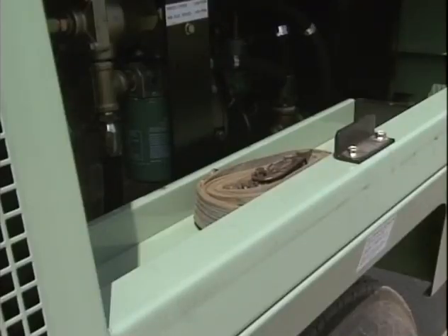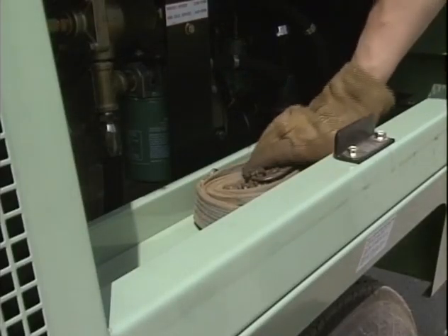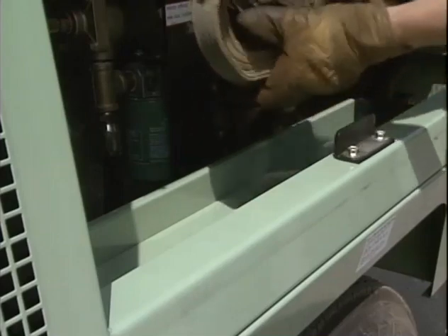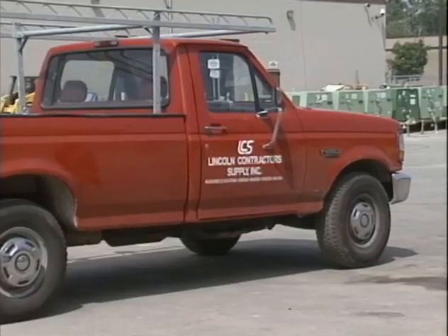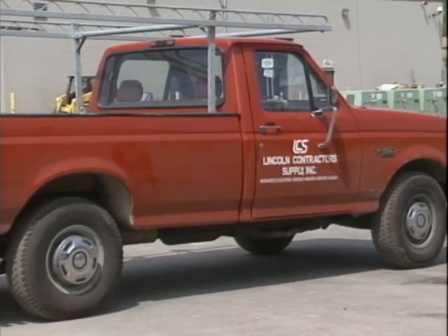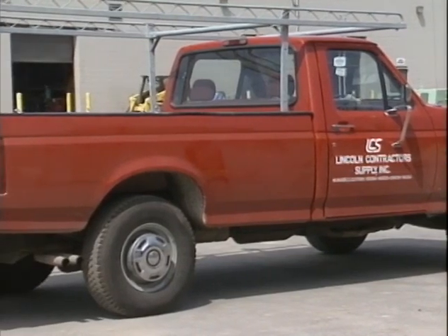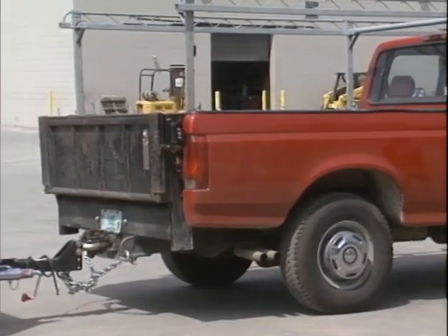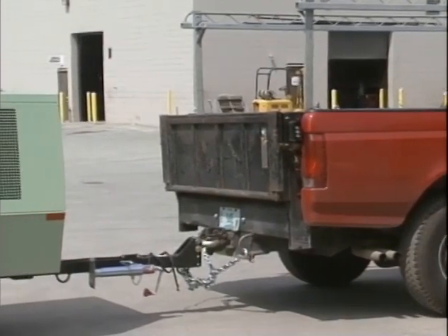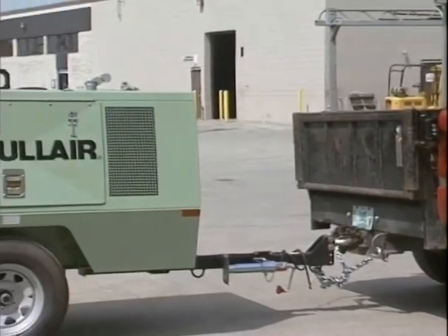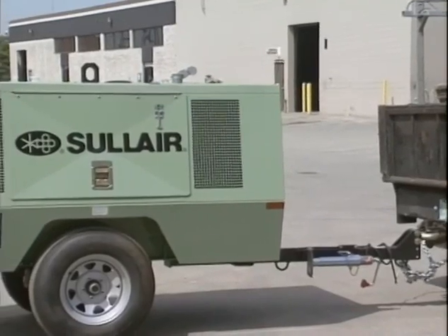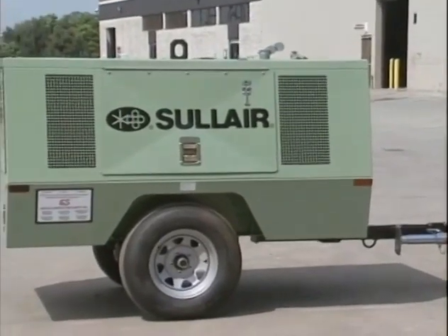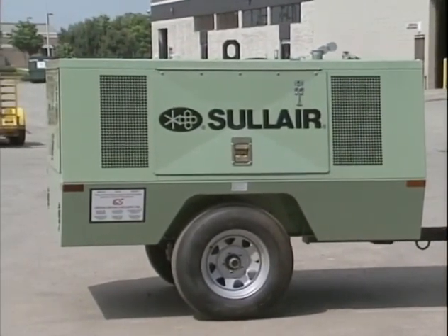Do not carry loose or inappropriate tools, equipment, or supplies on or in the air compressor. Do not permit personnel to ride in or on the air compressor or drawbar. Make sure the areas behind, in front of, and under the air compressor are clear of all personnel and obstructions prior to moving in any direction. Do not permit personnel to stand or walk between the air compressor and the towing vehicle.